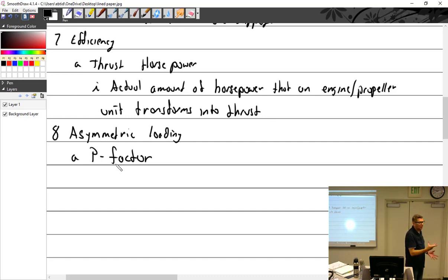You can't just take a protractor, zero it out, and say, look at that, that's got quite a bite, then come over here and say, this one's totally flat, we'll make this one the same as that one. By the time the plane is level, you have mismatched blade angles. That's why I bring up P factor: on this side of the airplane, when the tail goes down, the angle of attack increases, and on this side, it decreases.